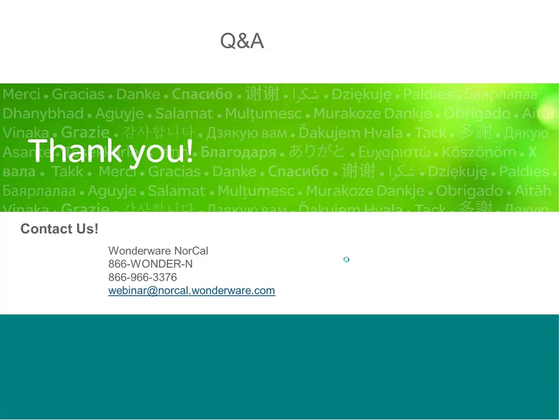Or you could use the VPN client that comes with your VPN appliance. For example, from Cisco, there's a VPN client called AnyConnect. That's the one I use. Another way to access your SCADA system in Wonderware from your iPad would be through a remote desktop app. For example, Microsoft has a free app called RD Client, Remote Desktop Client, and that allows you to do remote desktop to your server to access InTouch.